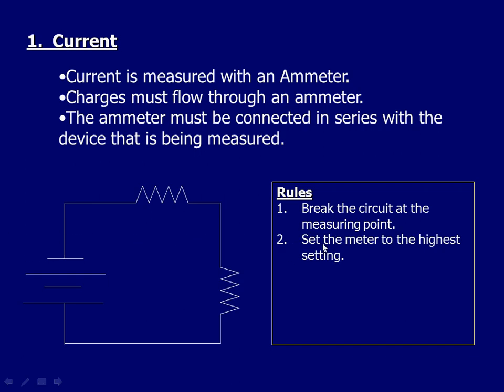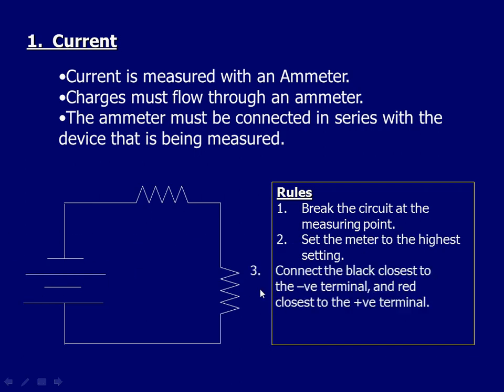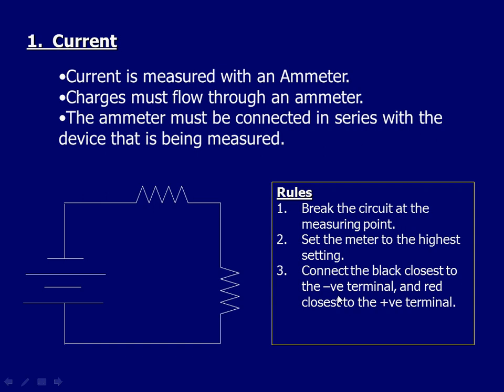Set the meter to the highest setting. Connect black closest to the negative, black to black, and red closest to the positive. Now, select the highest setting. I'll let you write that down.